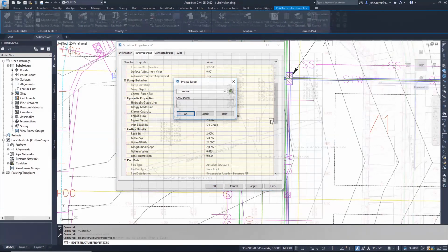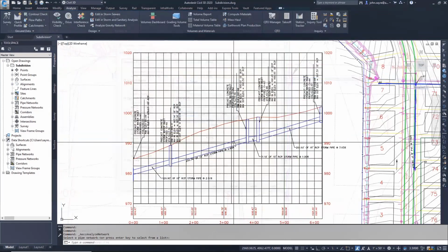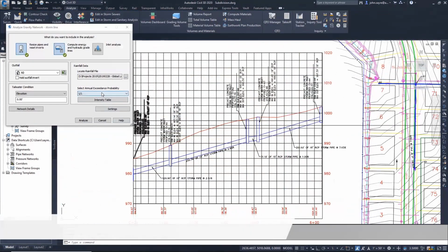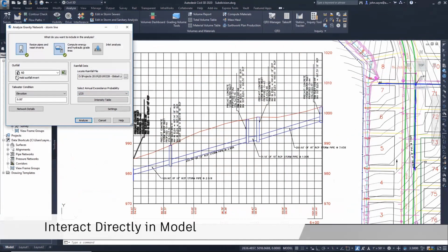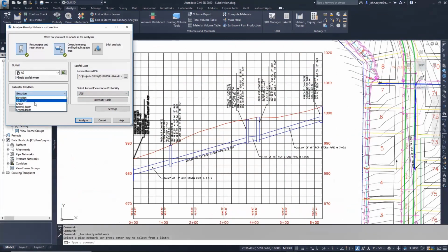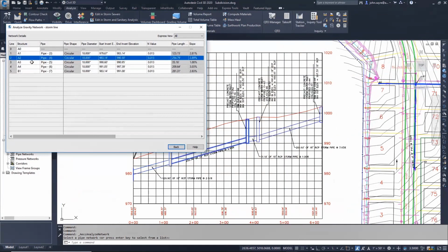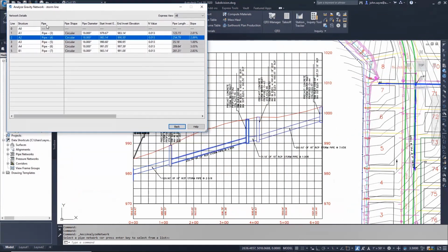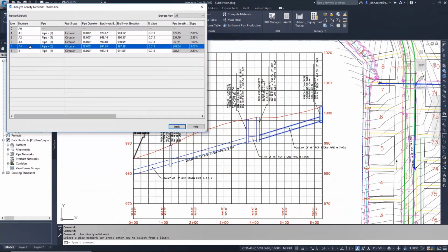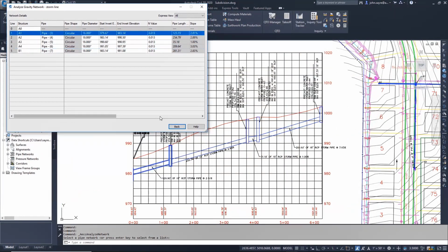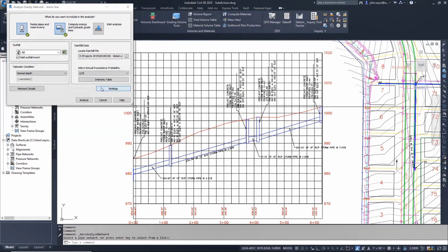Remember that with a known area, we can apply different formulas like CIA to give us the corresponding flow within that particular area, and of course that's after having performed our catchment area analysis. Then you can start looking at the specific pipe network structures, both in plan and profile, and start specifying the various parameters in terms of flow.